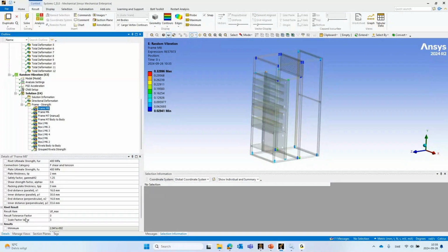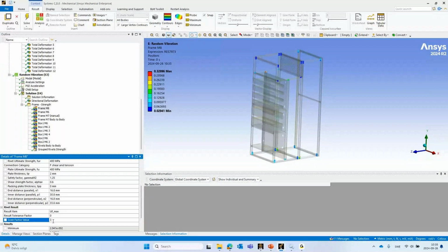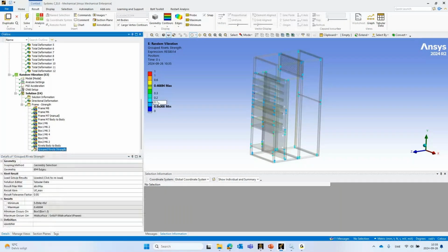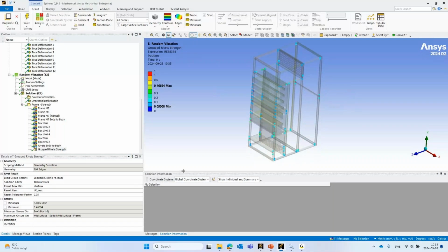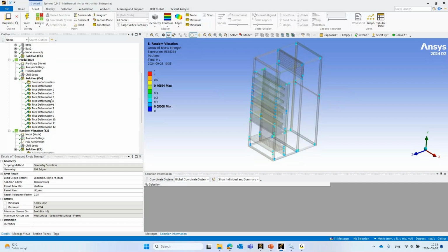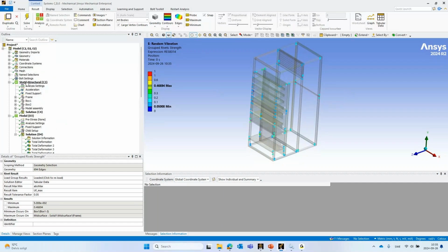In this case, with the 3 sigma probabilities, meaning that in less than 1% the loading might be higher, this plot here would then show that the vibration utilization is 0.46 at maximum. So in this case, the vibration wasn't a problem, but this big peak acceleration from the static analysis was critical.